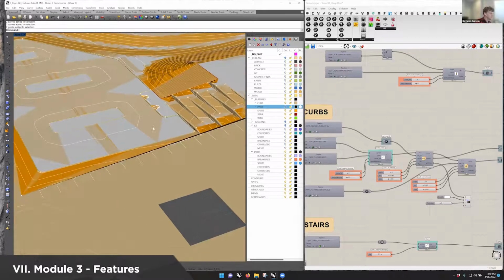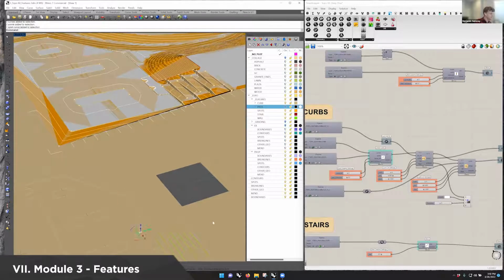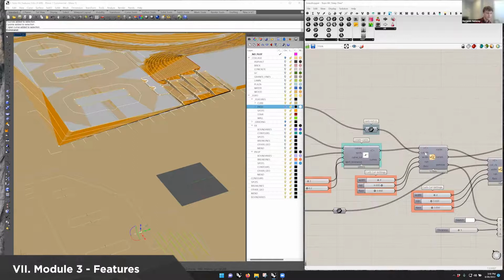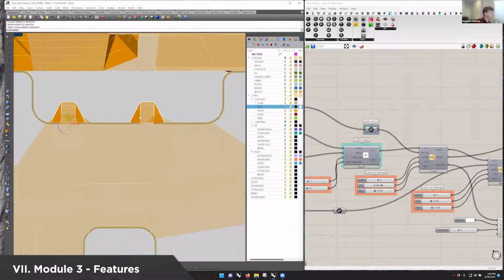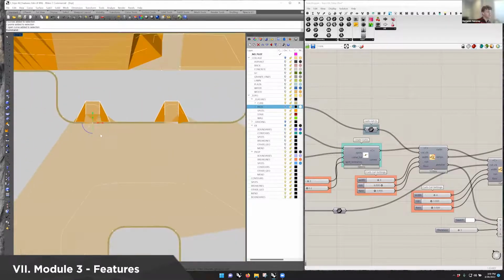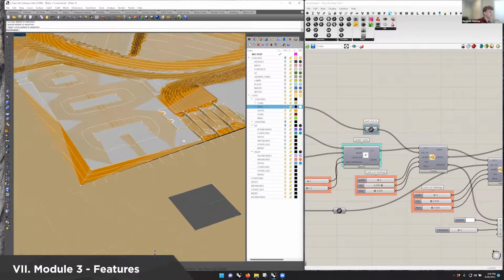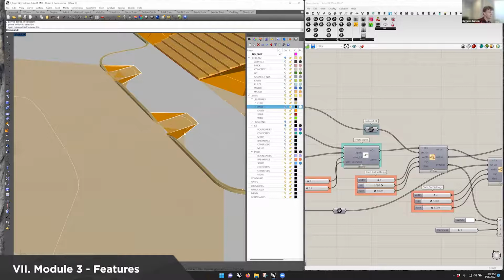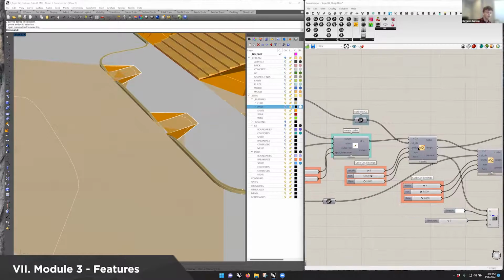All it's doing is you use a single curve, which right here we're using the curb cut center line being processed in. And everywhere that we have a curb cut center line crossing over top of a curve, it's just generating a curb cut for you automatically in 3D space, and it's regrading that space for you accordingly. And then you have a few parameters that you can adjust of the width of the curb cut, the run of the curb cut, and you can control this flare as well.